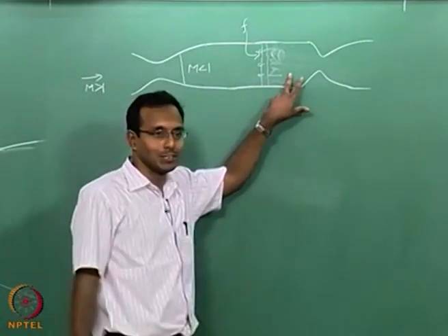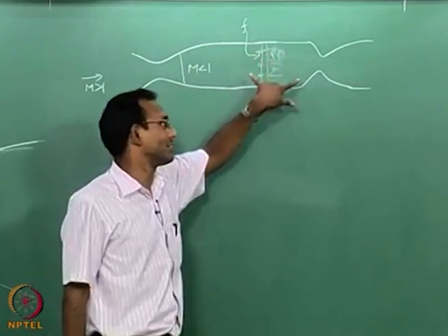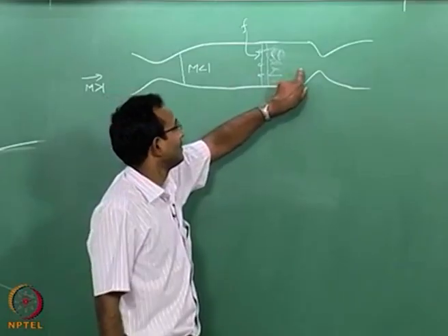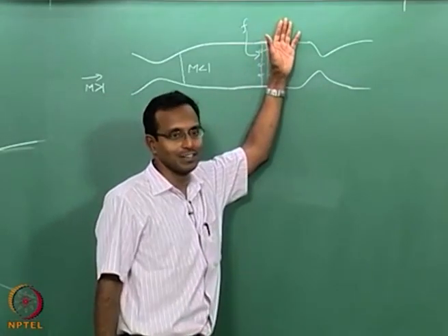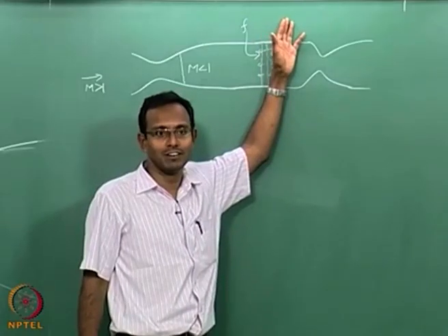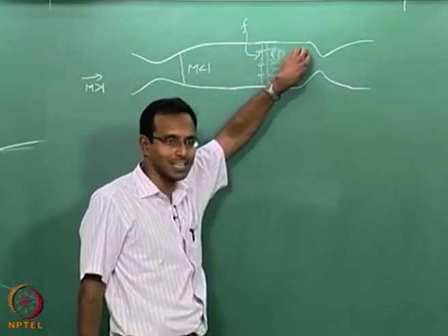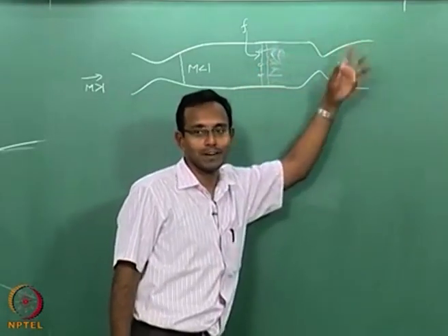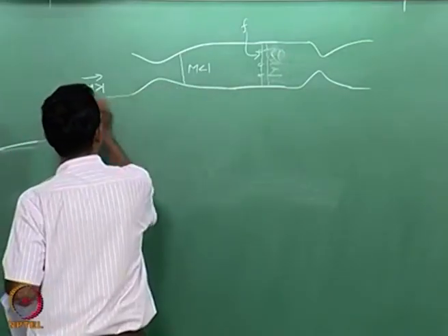After the burning, now it is subsonic, so it is a little easier, flow is going slow, combustion can happen within this length. And after that the hot gases are supposed to be expanded. From here if I think about it, it is like a rocket nozzle problem we did in an example, right. There is a chamber where there is high pressure, high temperature gas produced and that is going out through a nozzle, expanded out, and this is how the thrust is produced in this particular situation.